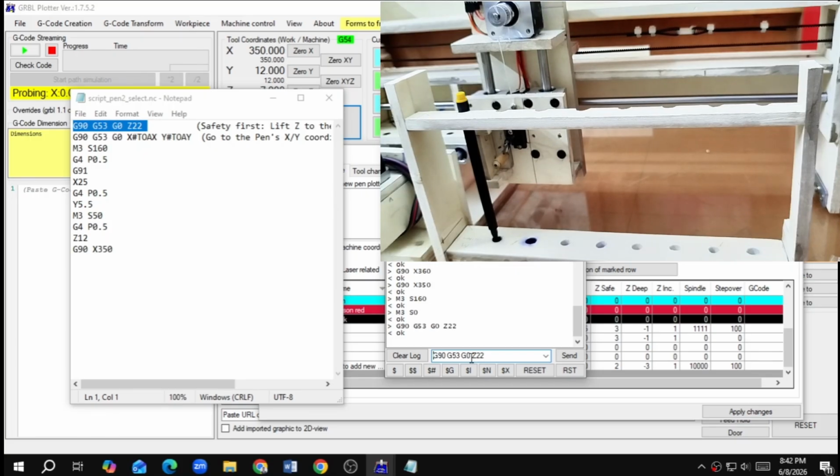If you keep the gripper at too much height, the pen may not touch the paper. So you need to give a few trials to see at which height it works best. And if you set the gripper too high, it may not insert into the pen holder. So a couple of trials and errors are required. Now my gripper height is set.